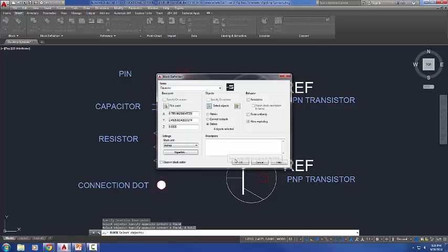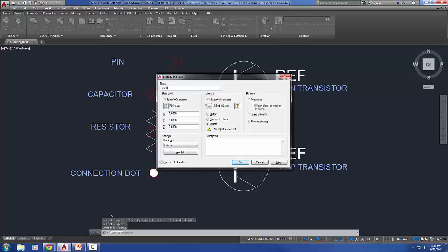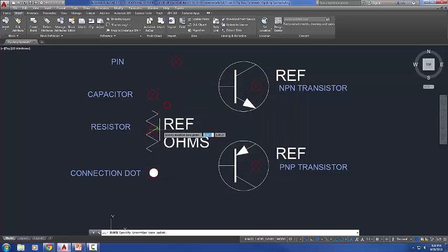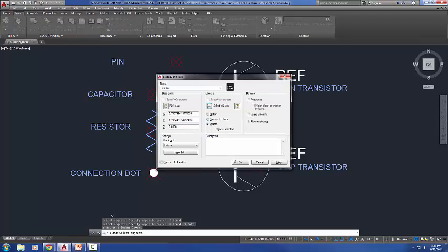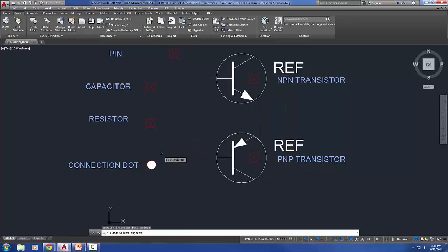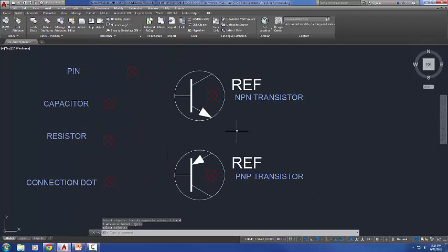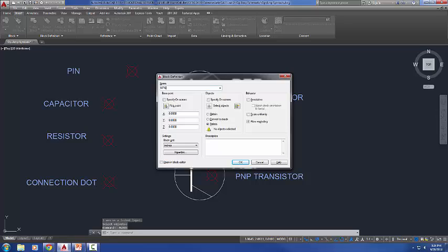What that does for you is, if it's checked, whatever layers you happen to have on or off right now are going to be on or off whenever you set this view current, and you don't want that to happen. So uncheck that. It's really fancy stuff. It's great when you're a little more advanced and you can incorporate layer states with named views. The rest of this we don't have to worry about. So really all you have to do is give it a name, define a window, uncheck that box. Be sure to select the new East UCS that I created, you can see it's what it's going to be using. And I will just say OK. And OK, and I've completed that one step. I'm going to repeat this same process several times. So a new 3-point UCS.